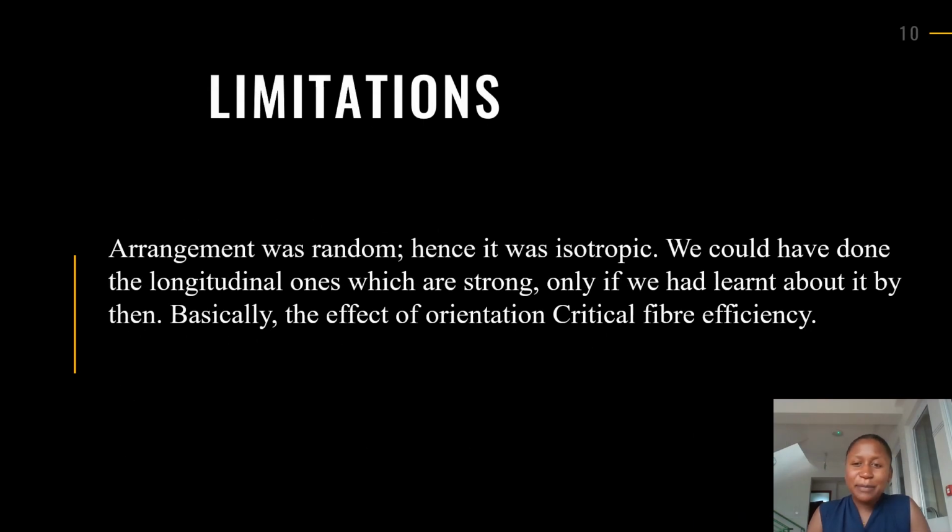So I'll move on to the limitations. Basically our arrangement was random, hence it was isotropic. We could have done the longitudinal ones, which could result in stronger structures, basically tougher ones. But by the time we did it, we hadn't learned about it. So basically the effect of the orientation of fiber efficiency was reduced, because the ones which are longitudinally arranged, using the critical fiber efficiency formula,